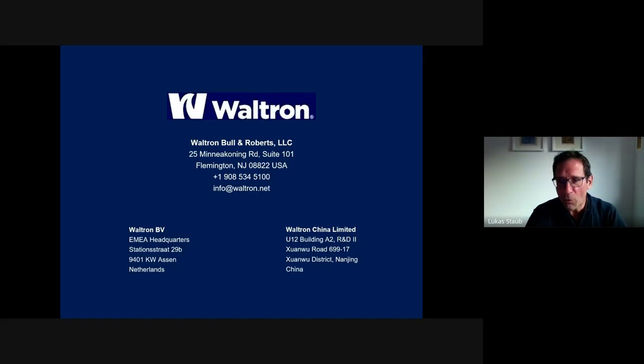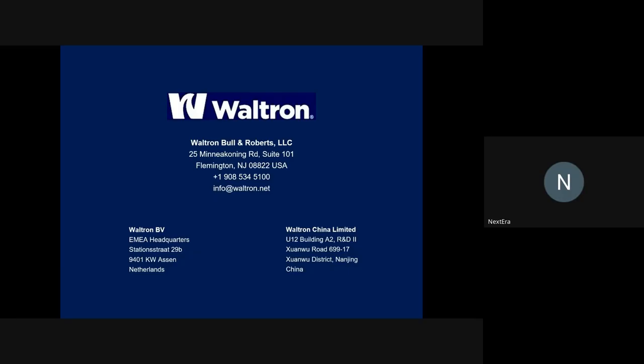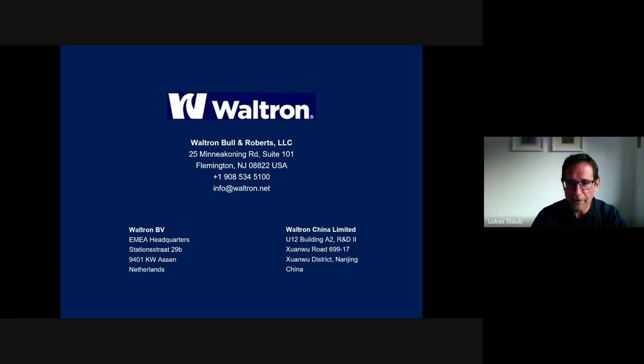What you don't want, of course, is an online sample, like what you do in a water steam sample panel, where you have a sample actually extracted from the process. That's definitely not what you want. But we see both. We see that people like to have a bypass line that actually goes back into the process, just so you can isolate it for maintenance purposes. But other than that, you can actually put it directly in the loop. Thank you so much. Thank you.